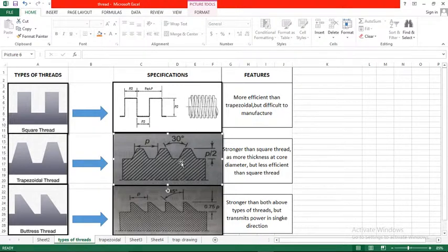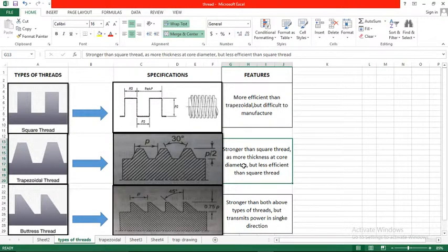And why does that happen? This happens because of the radial pressure, or the bursting pressure, it applies on the nut. Whenever we tighten them, there is some kind of pressure that actually reduces the tightening torque for this bolt.